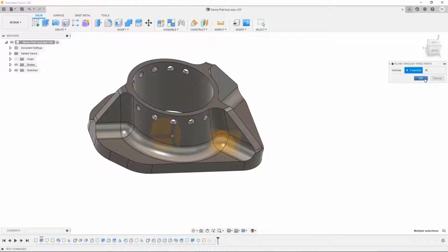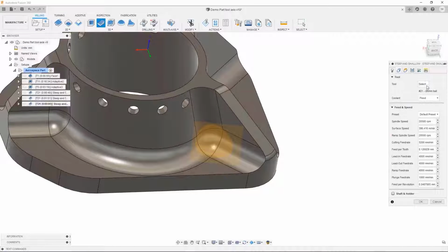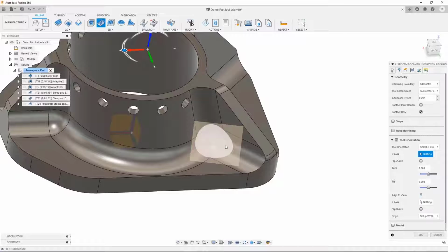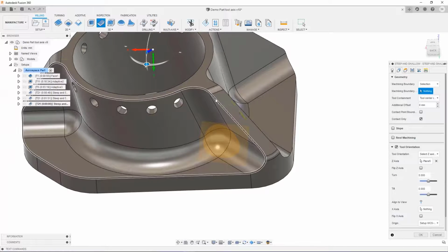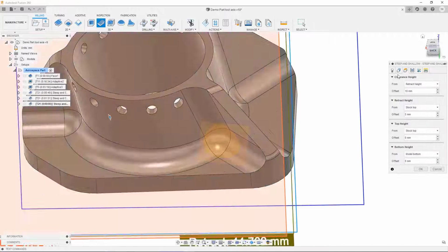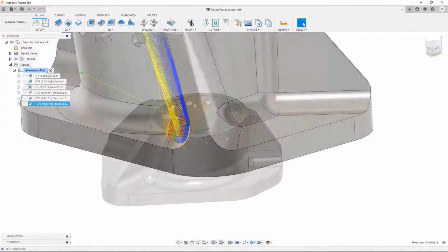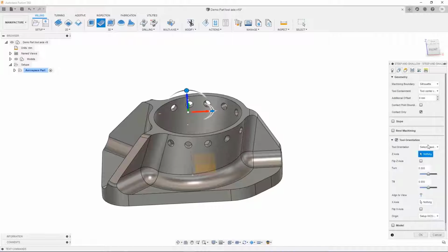Currently in Fusion, we can do this by selecting the Geometry tab in the Toolpath setup and orientate the tool direction by selecting model-based geometry features, such as faces, edges, or cylindrical surfaces. We have now introduced new functionality inside the tool orientation options to give you easier control on how to orientate your tool axis. The first of these enhancements is the ability to use surface normals to control the tool axis.